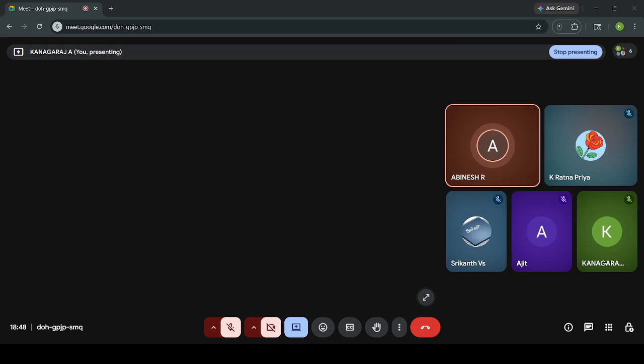Next, small outline package. A small outline package is similar to the SOT, but it is mainly for ICs. We have also seen the small inline package and the small outline package. Dual inline package, sorry guys, has chips where the component leads are plated through hole, but small outline package is SMD. That is the difference.